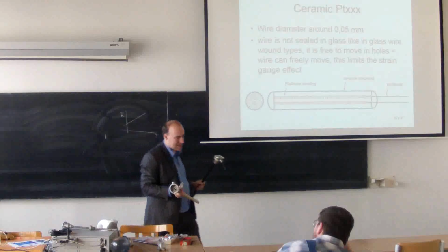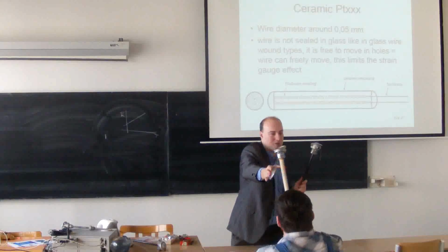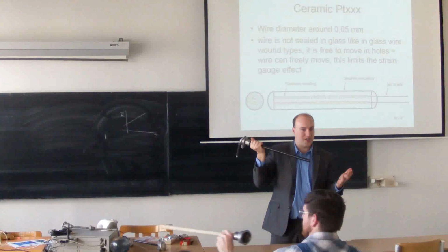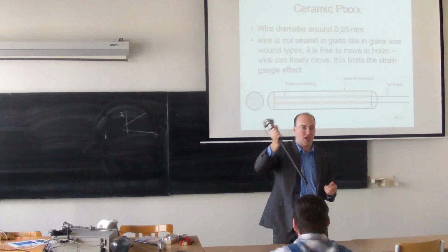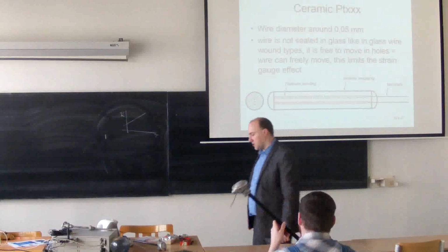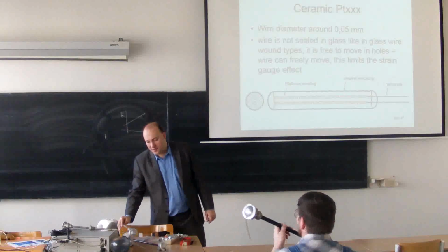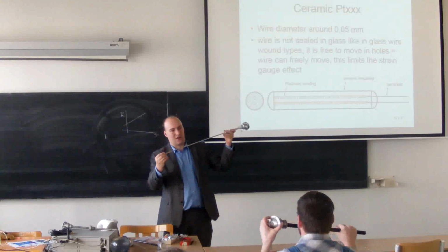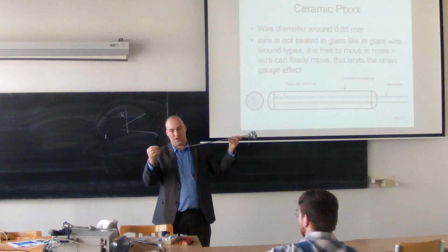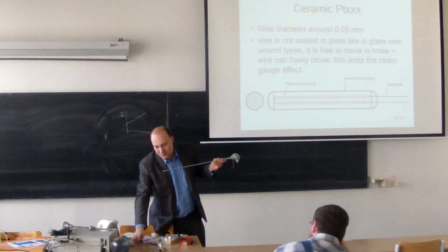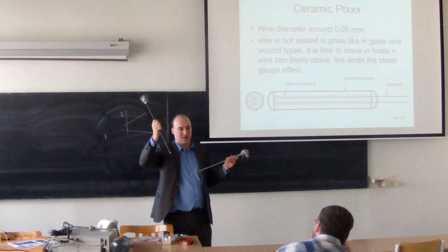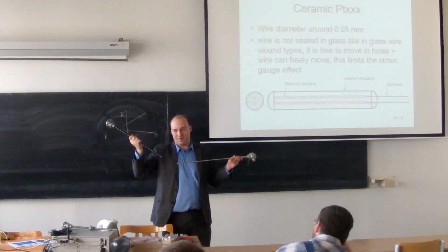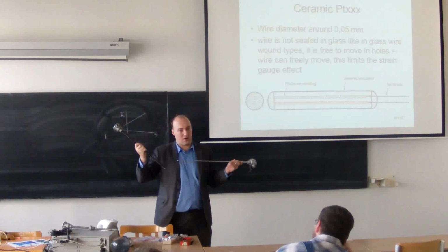We will also discuss how the thermowell is changing the properties of the sensor. It's clear that it will not change static properties, but it will very much change dynamic properties. Because it's clear that if I take a thin thermowell like that, it will take a shorter time for the heat to be transferred from the liquid to the sensor than if I take a thermowell like this. So the thermowell will protect the sensor, but will make the response time longer.